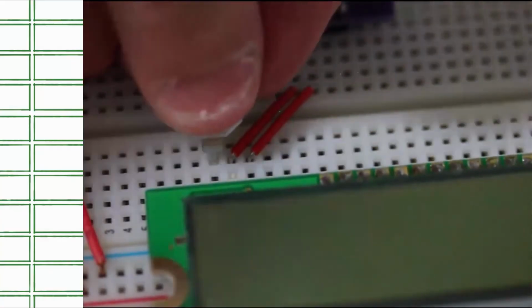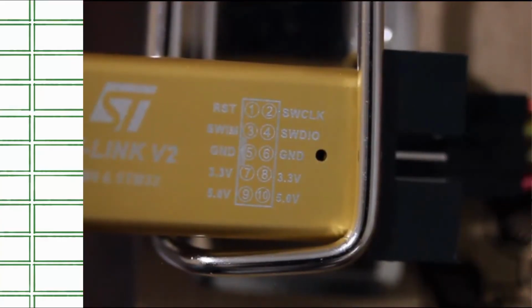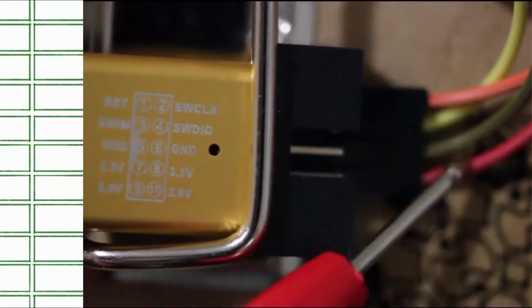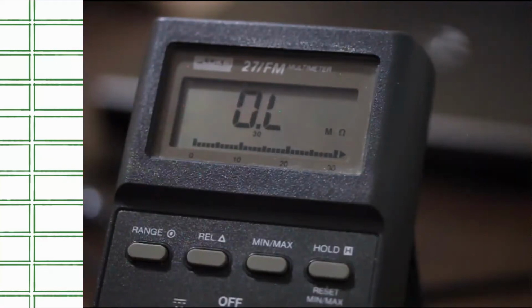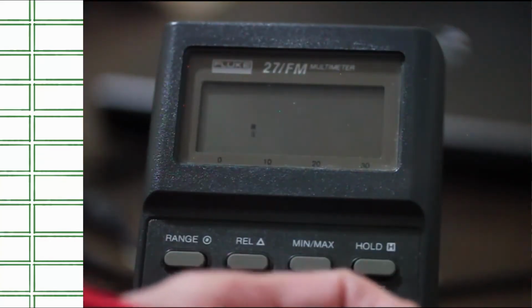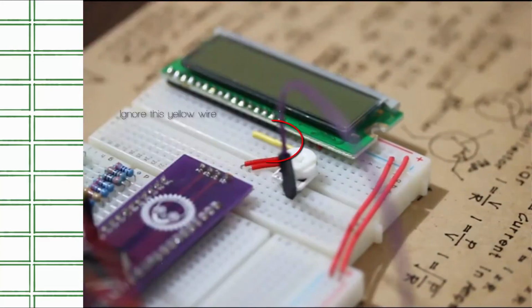This side still needs to be put in. So we can see that we have the 5 volts just below the 3.3 volts. And I have the 3.3 volts right here. So we can just plug one more in and we'll have a 5 volt. Before I connect it to the breadboard, I'm going to test it with the voltmeter, just to make sure it's outputting 5 volts. Okay, I got 5.14 volts. That's good. To convert my female header into a male, I'm just going to take a header, even this out a little bit, and plug it into one end of the potentiometer.